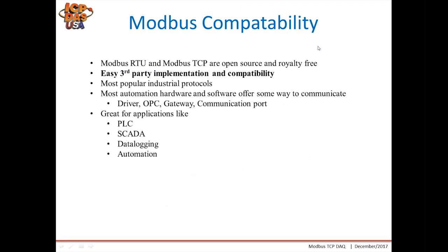Modbus TCP compatibility and Modbus RTU, because they're open source and royalty free, you're easily able to connect to third-party Modbus devices, and many of the most popular manufacturers already have communication capabilities to Modbus RTU and Modbus TCP networks. Modbus RTU does require a physical COM port connection, so you would need to have a COM port and a driver built into your hardware.